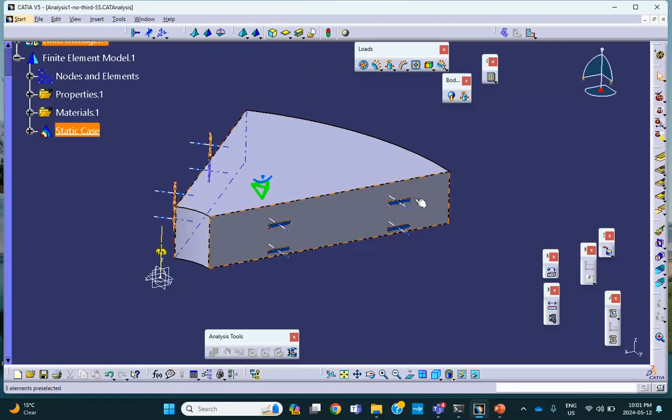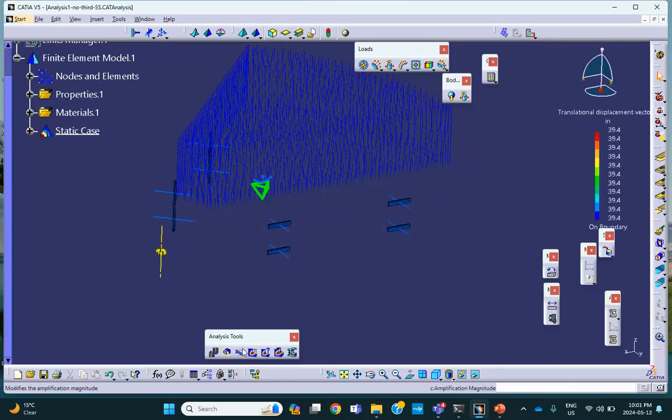Before, in the first run that I made, the middle of this was a surface slider. It could not go up and down, but here it does. So basically, we have to remove the rigid body motion. Now, if you're not sure why it happened, you still can plot the deformation and displacement. Let me plot the displacement for you. It looks like that. And if you animate it, you can see what happened.